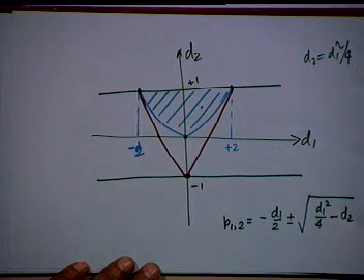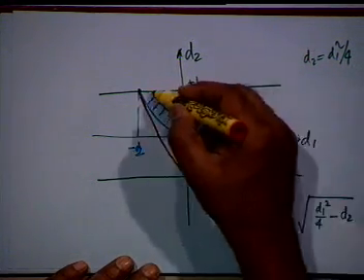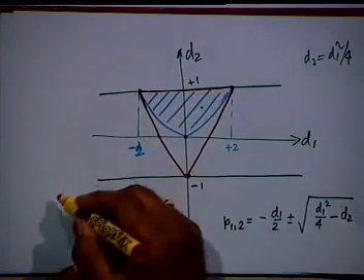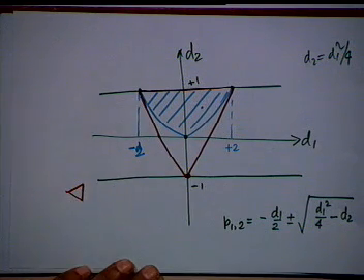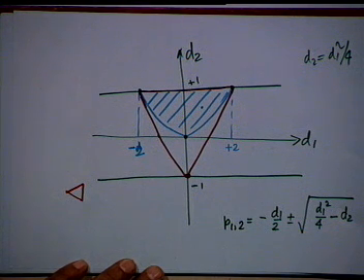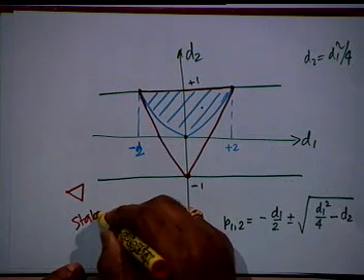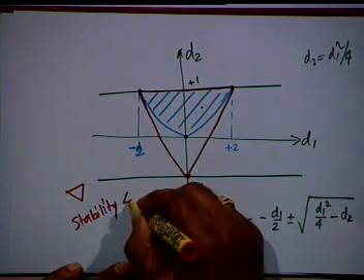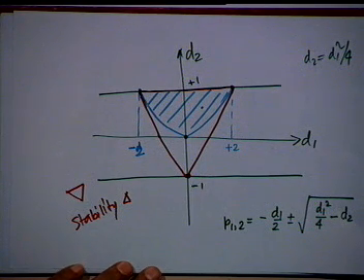Okay. So, this triangle, the red outline triangle, is the part of the parameter plane in which the second order transfer function shall be stable. In addition, this is called the stability triangle for a second order IIR transfer function. Okay. This is the stability triangle.